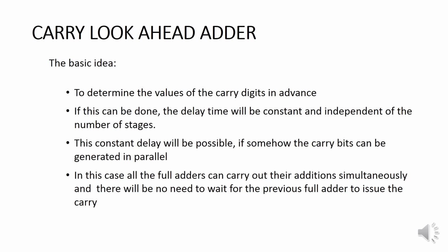They concluded that this constant delay will be possible if somehow the carry bits can be generated in parallel. If we can do that, then all the full adders can carry out their addition simultaneously, and they will not need to wait for the previous full adder to complete its task. This is the basic idea behind the carry look-ahead adder. The delay is reduced, but the trouble is that the hardware complexity increases because the amount of gates required increases rapidly. This is the drawback of this idea.